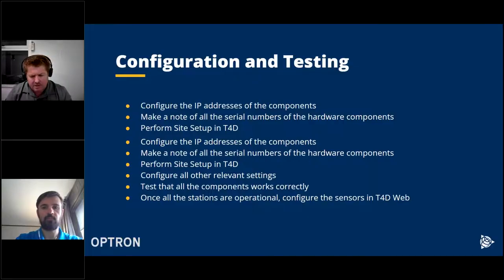And that means that even if it misses just one orientation beacon, that will cause a spike in your monitor data. So what we tend to do is we do the initial setup, and then we remeasure all the orientation, so that from the start, all the orientation and the total station position fits well together within this, let's call it, the localized monitoring network.